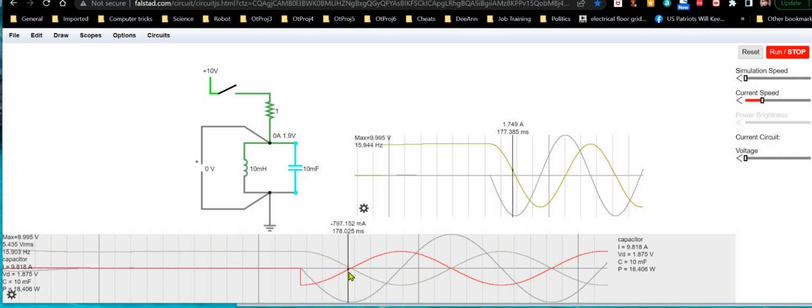Whereas an inductor with no current means it's dead, because an inductor does not hold its energy unless there's a current flowing through it, so it has to actively have a current through it. Unlike a capacitor, which, an ideal one, will hold its energy forever. But an inductor, you can't store that without something like a superconductor to maintain that current flow forever.